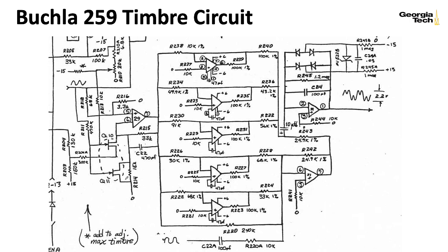But notice that this resistance is in parallel with this JFET. Roughly speaking, as we change the voltage being applied to the base here, we're effectively changing a resistor-like thing that's in parallel with this 15K resistance. And that's how we're able to vary the gain of this circuit here.